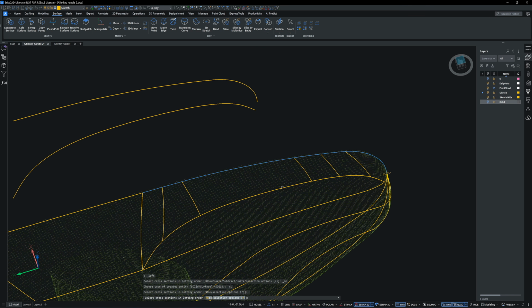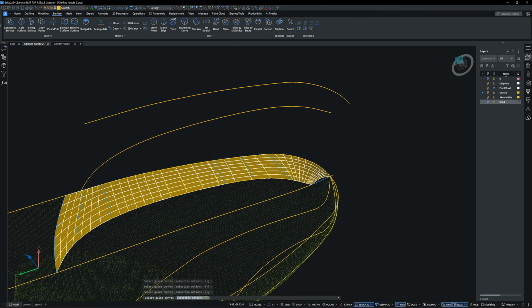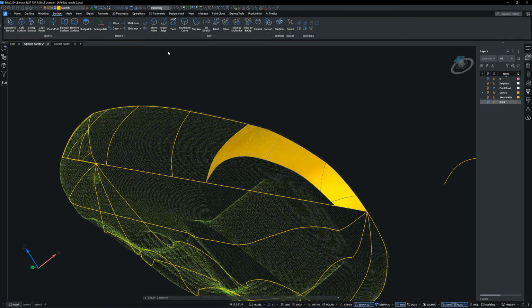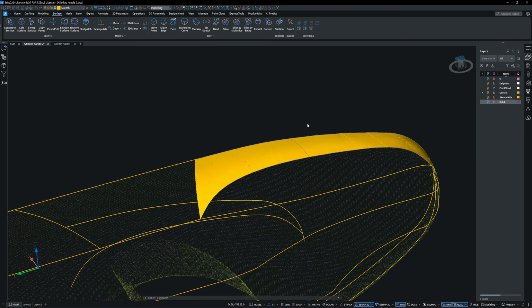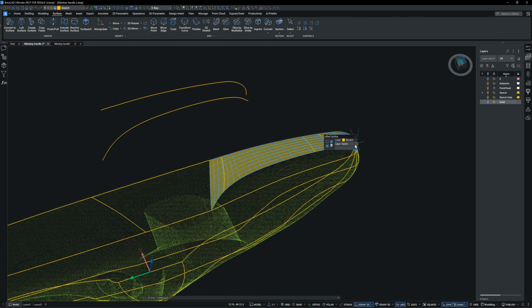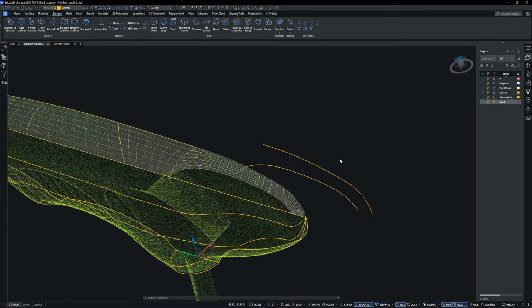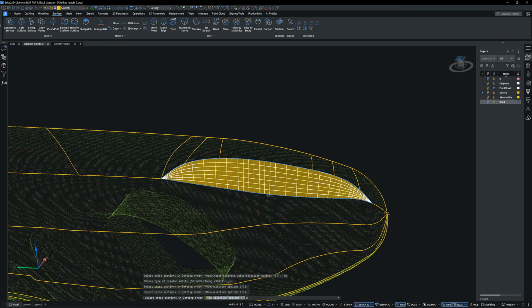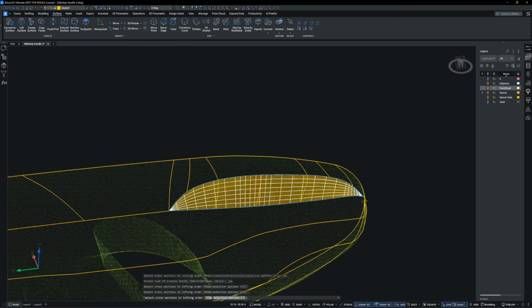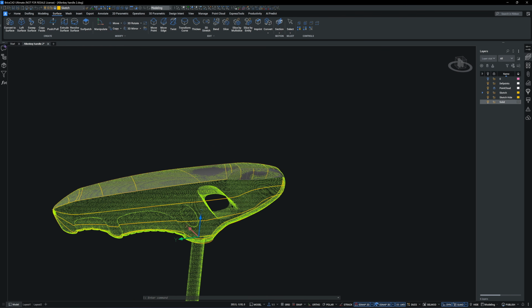I tried adding more guide rails several times to better understand how the surface loft function works in BricsCAD. This is actually my first time modeling entirely with surfaces in BricsCAD. I placed the surface segment I created on a separate layer so I can quickly toggle its visibility whenever I need it. If you want a smooth, blended surface without standout edges, you will need to experiment with each segment, deciding where to break the boundary and where to place guide rails.